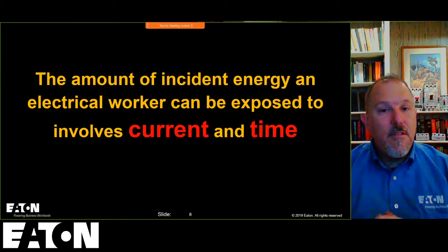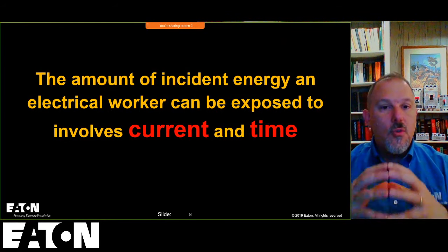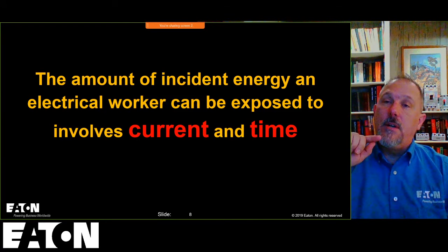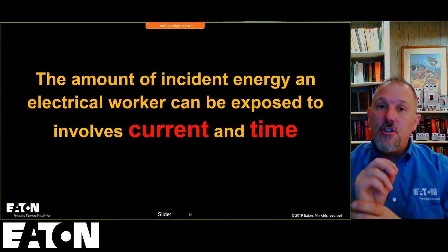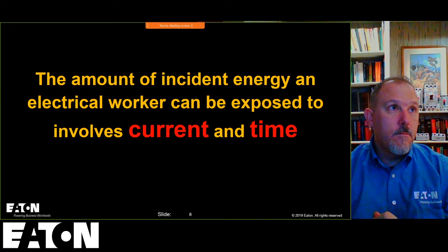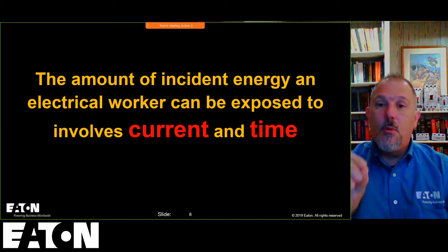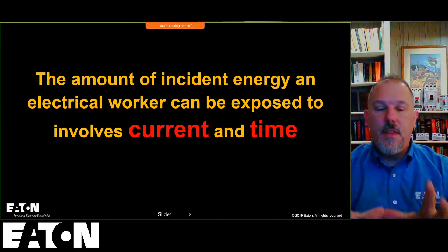Now, the amount of incident energy that the electrical worker can be exposed to involves current and time. And I'll tell you, based upon the recent editions of IEEE 1584, the current and time are important, but also the size of the enclosure.